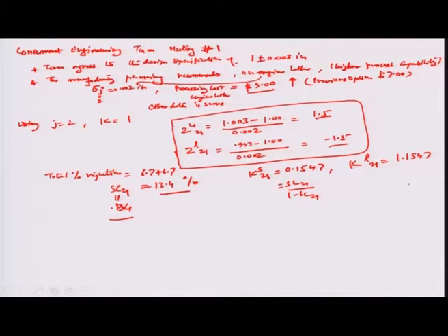So, having obtained this, we accordingly find out the number of units scrapped in this particular case, on the suggestion of the manufacturing planning, which is involved at the very beginning. The number of units scrapped here is 0.1547 times the output level of 1000. So, about 155. This is much lower than the 465 earlier, as you see.